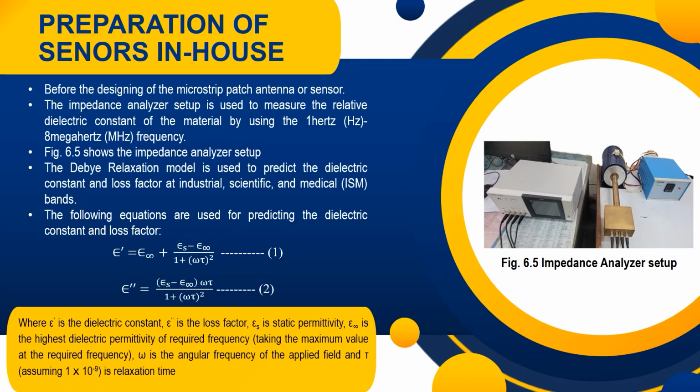Whatever sensor we plan to have, we use this data to feed into the HFSS module of ANSYS, the High Frequency Structural Simulator software, and basically we can calculate the dimensions of the ring or of the microstrip patch antenna. Otherwise, I can use a mathematical way for calculating the epsilon r using a ring resonator test.